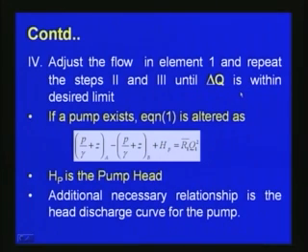So, for delta Q, when we do the iterative procedure, we can set the prior value, say 0.005 or 0.0005, like that we can put some value. Then when the computer does the iteration and reaches this particular limit, the iteration is stopped and we finally get the value. So, that is the iterative procedure we generally adopt for these kinds of problems.